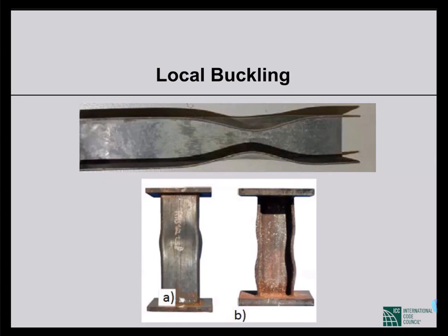And whenever compression is induced in whatever forms, that tends to make the steel sections buckle. So that is why we have to always be very careful about buckling. Now, there are different types of buckling, I'm sure that you know that. One is member buckling, that is column buckling, where the whole column buckles, right?